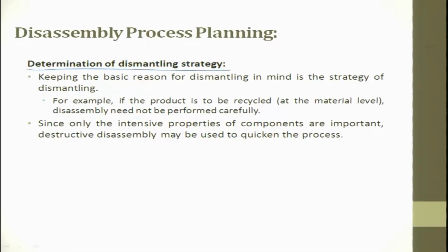We have seen the first three points here: product analysis, assembly analysis, usage analysis, and now we are trying to see the determination of dismantling strategy. Keeping the basic reason for dismantling in mind, the strategy is, for example, if a product is to be recycled at the material level, disassembly need not be performed carefully. That means you have already decided that you are going to recycle the material, so do not spend much time on it.